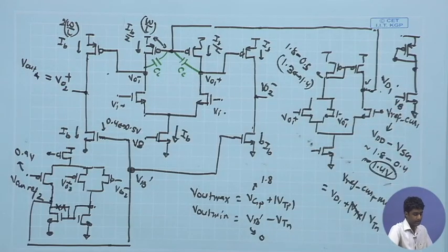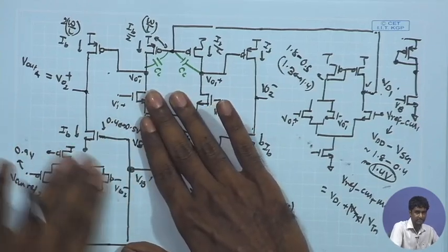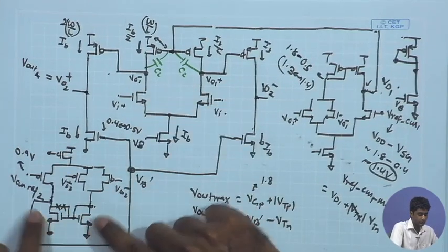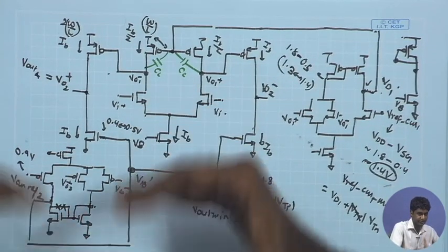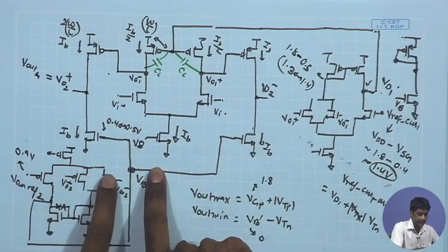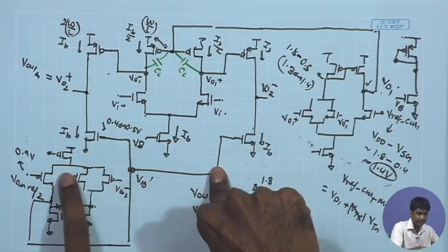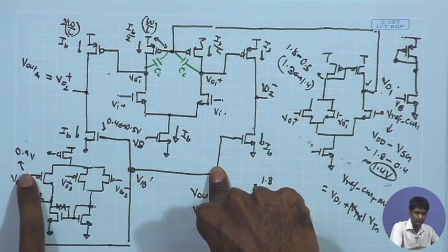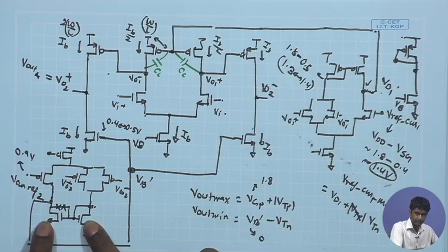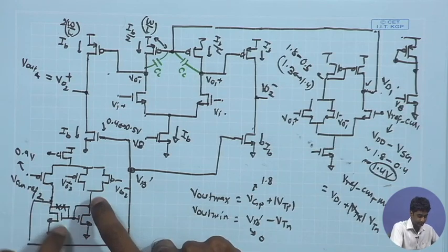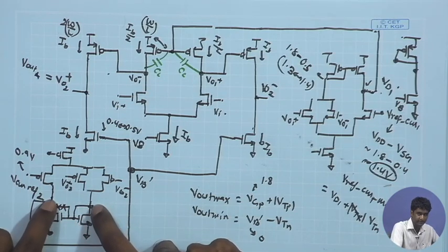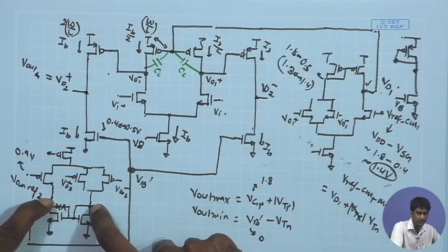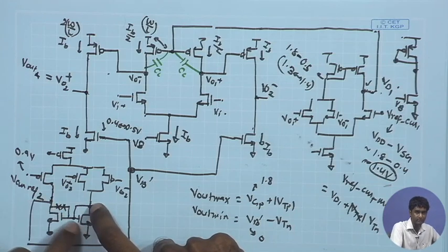And once again here we can see why we have chosen this NMOS load, because the output DC potential, if I just look at this as a differential amplifier with current mirror load, if I look at the steady state condition in which the effective DC potential at the gate of this PMOS and the reference PMOS is same, we are going to have same current in these branches approximately, and as a result the gate voltage being same, the drain voltage of these NMOS devices are also going to be same, which is going to be equal to VGS of NMOS.